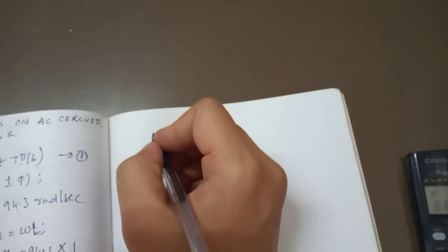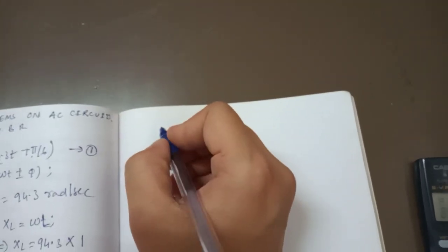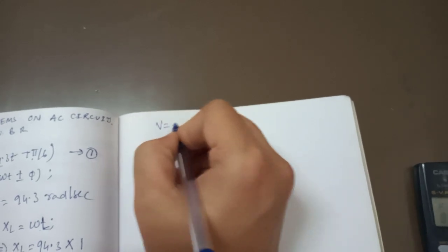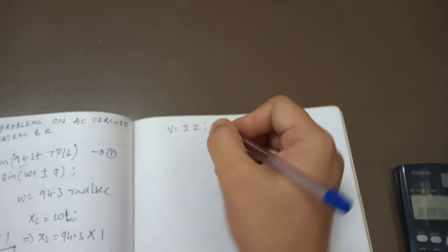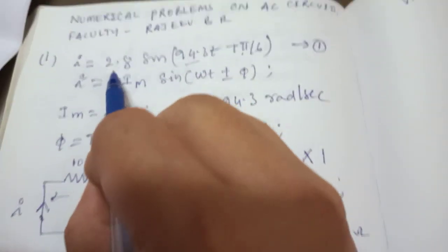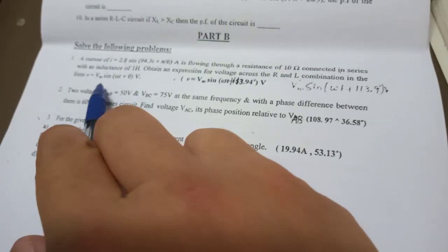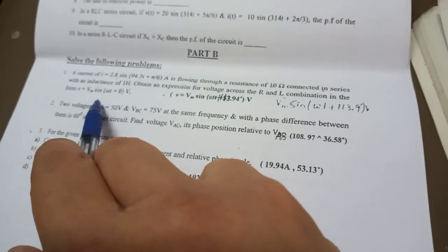I am repeatedly telling you, the key for every solution of any AC circuit problem is V is equal to IZ. But here I have the maximum value of I, and also I want to express voltage in terms of Vm sin omega t. So in the standard form I want Vm only, I don't want the RMS value. So I can write like this: Vm is equal to Im Z, right? So the ratio